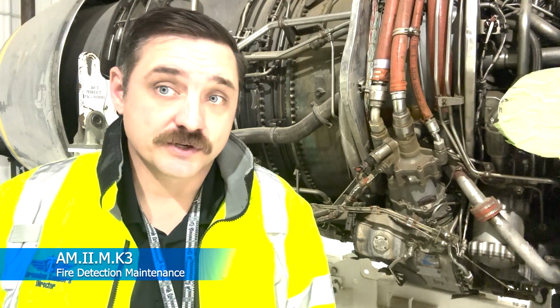You can also have on-condition situations where there's a fire alarm that goes off, but there was no fire, or you might get a maintenance code that says, hey, loop 1 of engine 1 is indicating a fire, but there's no fire, so that means that it's grounded, or the resistance is going bad, or maybe it's just old, and the insulation is slowly starting to deteriorate, allowing it to get more connectivity than what it's supposed to have. These are all basic ideas of how you could potentially be maintaining a fire loop.